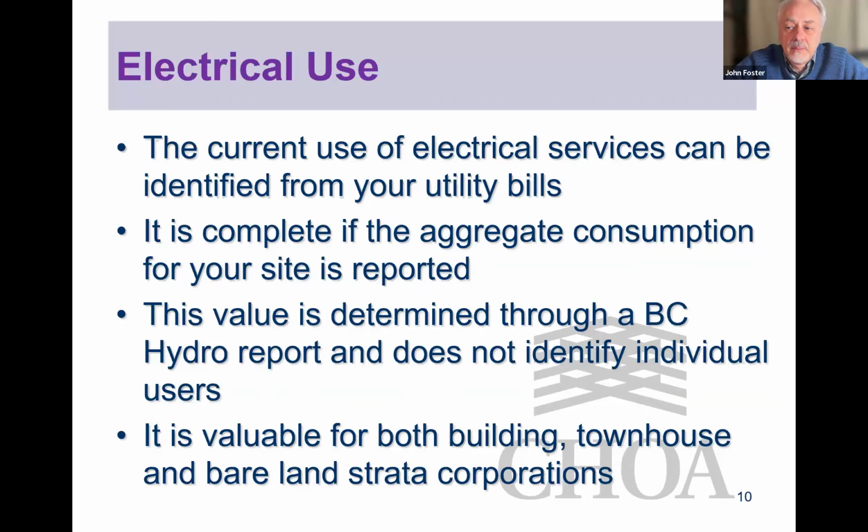So that may be giving you kind of a warning, a heads up, but you need to look at it more in depth. And some providers hopefully will actually look at the gas bills themselves and be able to project on the line what we call a heating degree day regression, which is the ideal way to do it. There's some simpler ways just to say that even though the boiler is that big, you don't have to put an electric replacement for it that's exactly the same size.